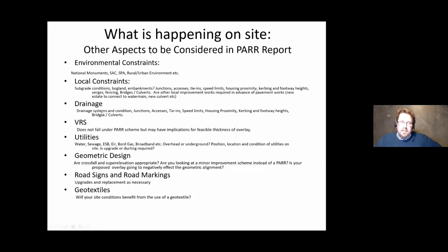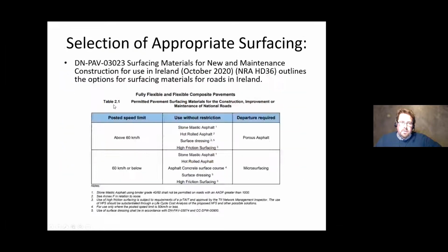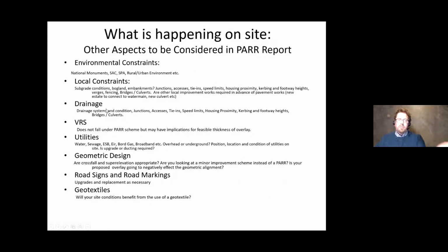Your drainage, as I said again, be conscious. Oh, sorry, I jumped too far forward there. Drainage, the drainage remediation, and your VRS. Again, make note of anything that's damaged, and be conscious of the height of it and the implications it will have for your feasible thickness of overlay. Again, be conscious of your utilities, and also very conscious of whether upgrades or ducting are required.